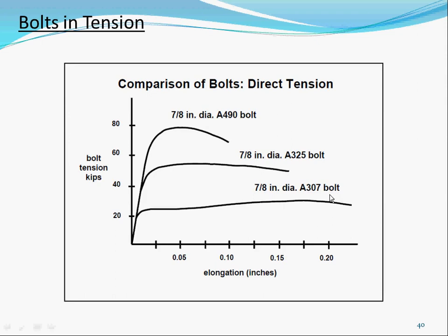The A307, we are using it, but only at the beam, the nailer connection on the top. The bolt is for the wood to the steel beam top nailer. The Fy is about 65. So this is a lower Fy.